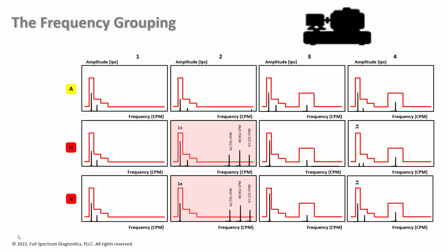We're going to bring our route data back into the office. We're going to dump it to our computer database, which has all the alarm profiles. And the red line here that you see, the stair-stepped version of an alarm profile, is what we'll be comparing the peaks in our spectrum to.